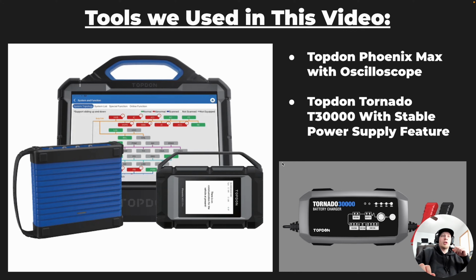So here are the tools we're going to use in this video. We're going to use the Topdon Phoenix Max with the oscilloscope. We're going to use the Tornado T30000 to work as a steady state power supply. Basically, this will hold our voltage steady on the battery even while we are performing testing with the key on, engine off, and it will vary the amperage as necessary to hold that battery voltage steady.